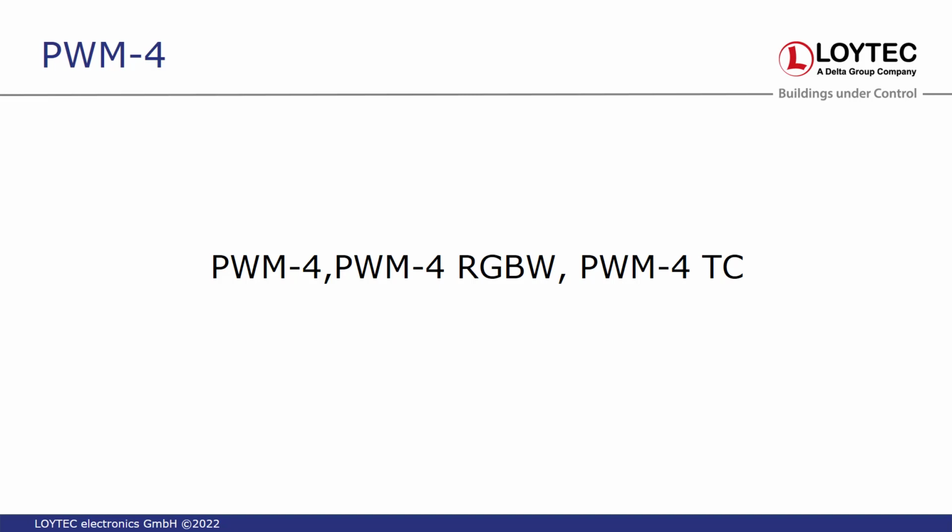So if you want pink, you have to choose some percentage of red and blue, for example. Sure. This is why you have the different models. I mean, you have the wrong model. Yeah, but it works. We made one installation, and it works really fine. But that's why we have the other ones. With the other ones, you will only see one DALI address, and then you have the right DALI commands, of course. It's basically the same hardware, like you say, but the firmware is different, so it behaves differently on the DALI channel.